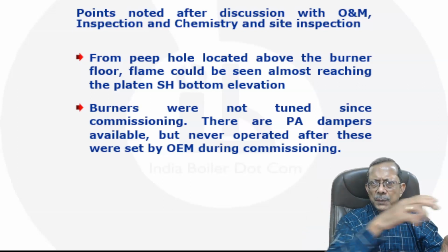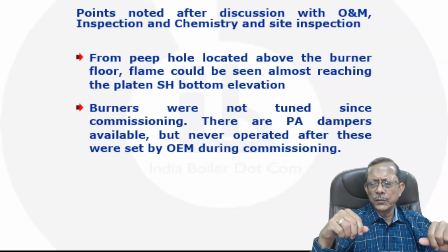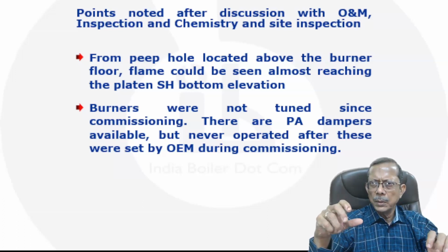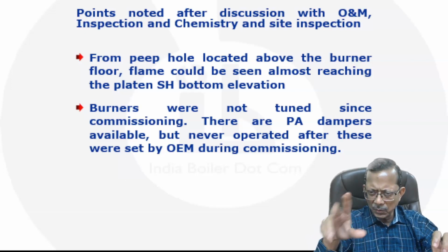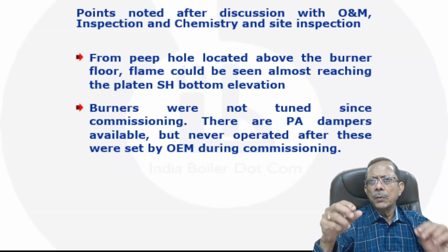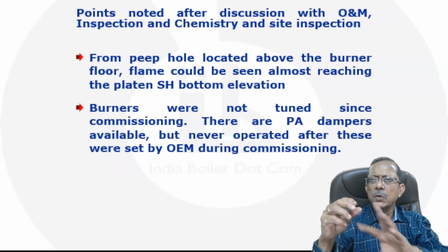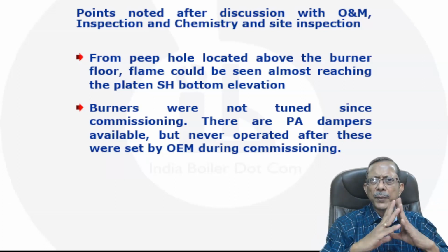If it goes up and down, moves front and back over the burner shaft. So that was basically the primary air control. When I checked the rotation, if I rotate it clockwise with two pitch of rotation, the number of slots which were closing was 10%, right? So it was closing with a clockwise movement.